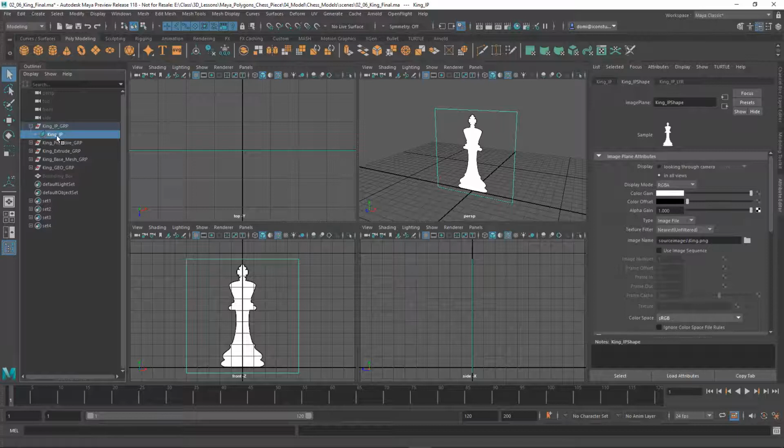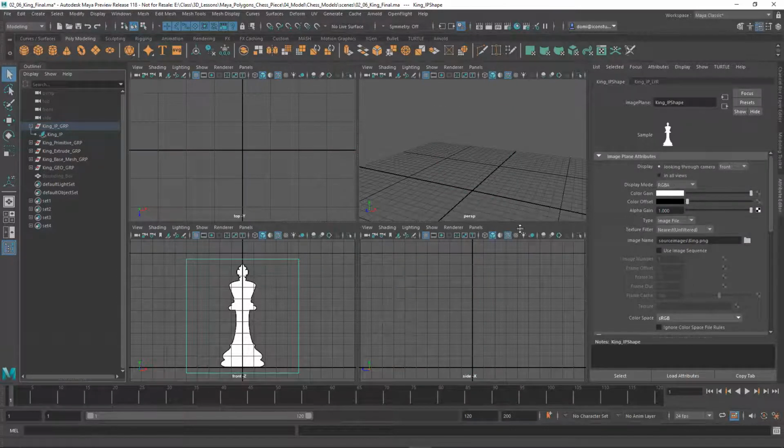All right, you have to pick on the object, don't pick on the folder or the hierarchical level, and that will trigger in the attribute editor, which is this tab over here. And just to review again, if you only want to have it in one viewport, then you just click on this button in display. Okay, so now it only shows in this view.